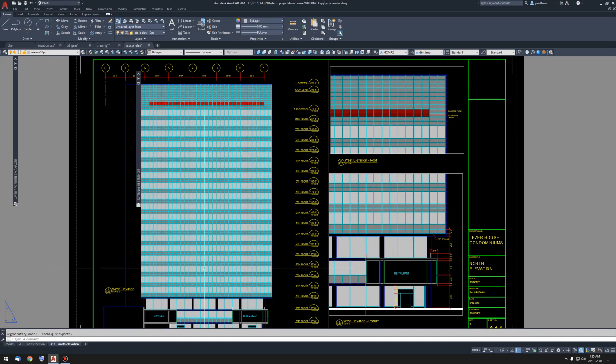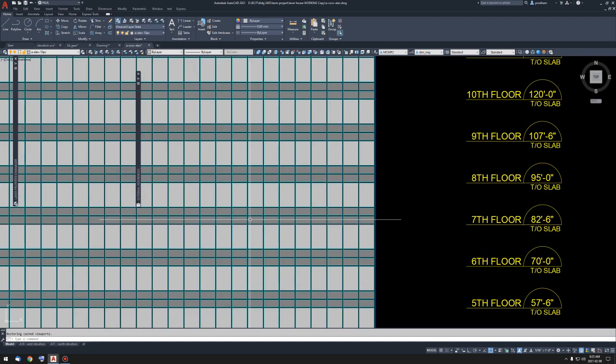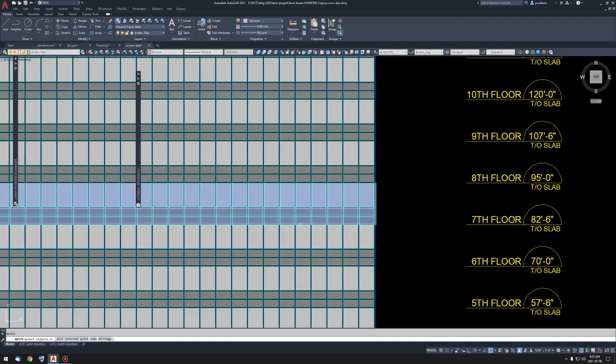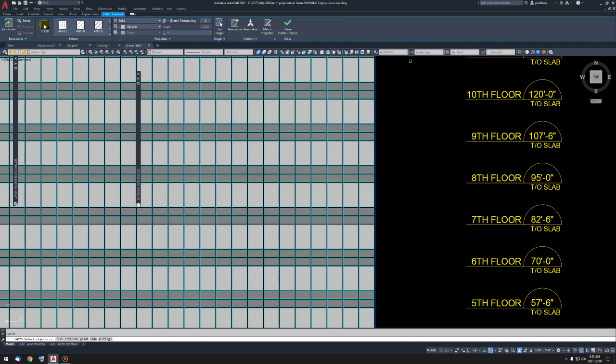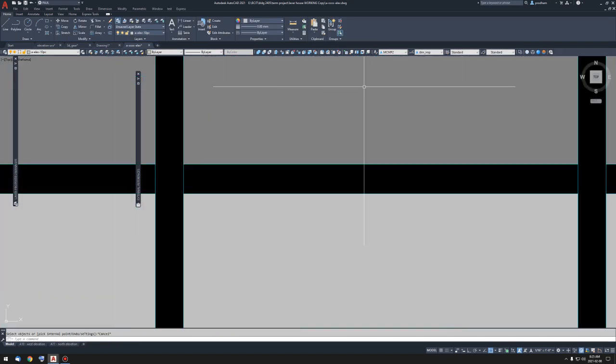Let me show you a problem people will have with, again, this goes back to CAD 1, solid hatching. When you go to hatch, I've got it set at home to always go to solid hatching by default, but for most people it's set to ANSI by default. And what that means is people end up occasionally doing really dense patterns when this is solid. You can see it's solid.